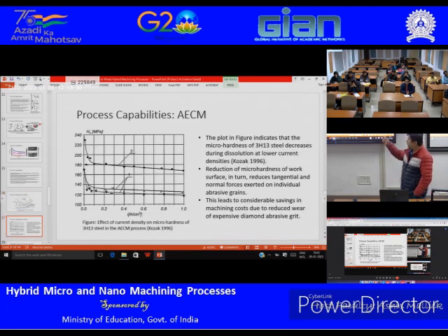But here, the benefit of abrasive assisted ECM over abrasive assisted EDM is that abrasive assisted EDM can have some harder surface micro hardness. On the other hand, if you do electrochemical dissolution, it actually removes the recast layer. Remember, for removing recast layer, electrochemical dissolution is a very effective process, even sometimes more effective than some mechanical abrasion. Okay, so it really can remove all the recast layer thickness, all the heat affected zone, and reduce the micro hardness of the workpiece surface.